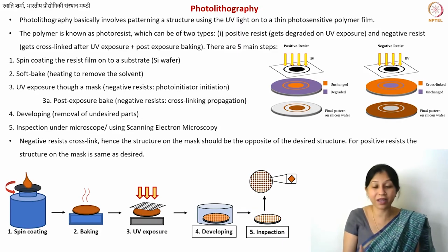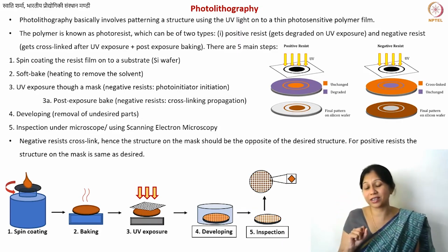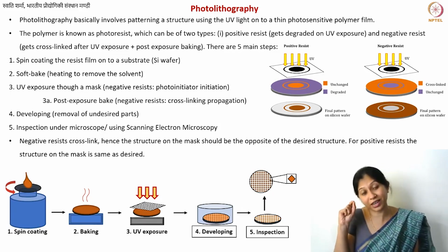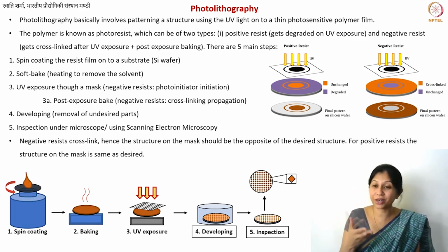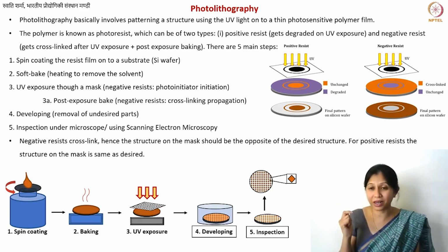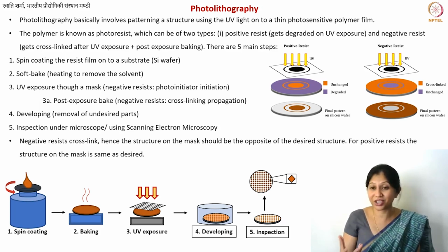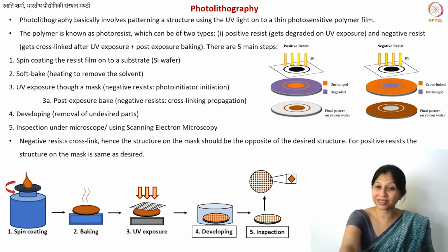So you can even sometimes carbonize micro scale structures, and now you get nanoscale structures. You did not really have to use a fabrication technique which was usable for nanoscale. You could just convert your micro scale structures into nano. So even that can be used as an advantage. The wastage of material is not that big a problem in the case of micro scale, because overall the usage of materials is much less compared to what you have in the large scale structures.